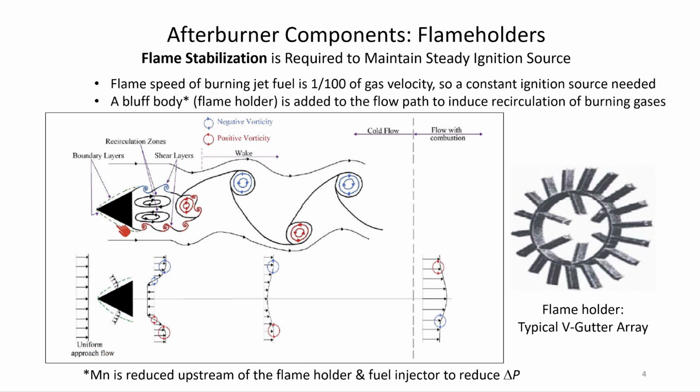And then this is the flame holder. It's an intentional stall. It's a pressure loss. It's inside the flow path. And if you look at the top picture over here, you can see that flow comes in from the left to the right, and there's a recirculation zone right in the wake of this bluff body. Now what we've done is we have lit the fuel, and now it continues to burn as long as there's fuel coming at this thing.